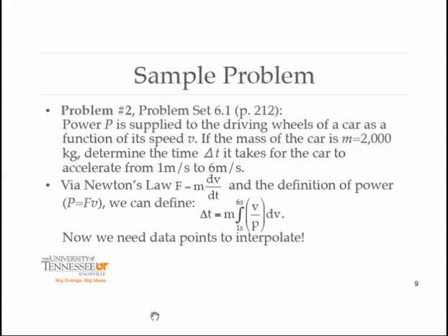The goal is to determine the time it takes for the car to accelerate from 1 meter per second to 6 meters per second. This is an application of Newton's law: force equals mass times acceleration. You should remember that from physics class. Acceleration is nothing but the derivative of velocity. Power is equal to the force times the velocity. So exploiting Newton's laws, power is equal to the mass times the derivative of velocity with respect to time,